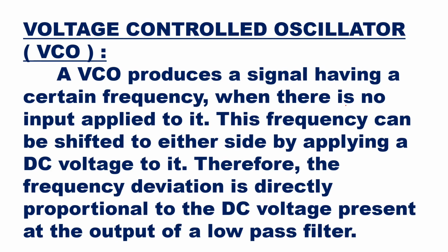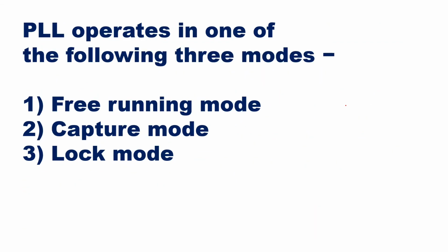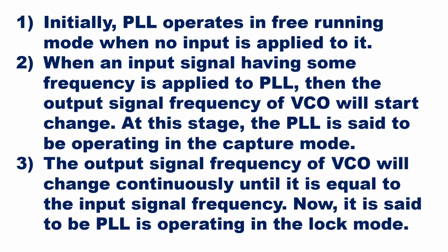Then if you look at the operation of the PLL, it operates in three modes. One is free running mode, second is capture mode, and third is lock mode. When there is no input frequency applied to it, the PLL is in free running mode. But when you apply an input having some frequency,